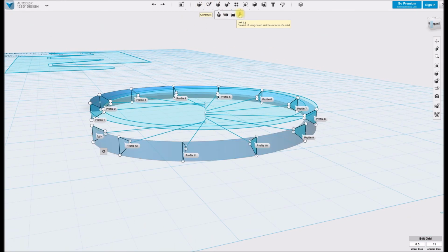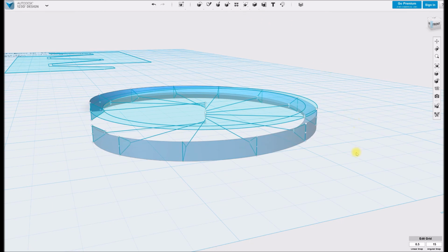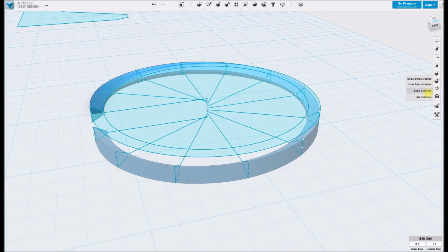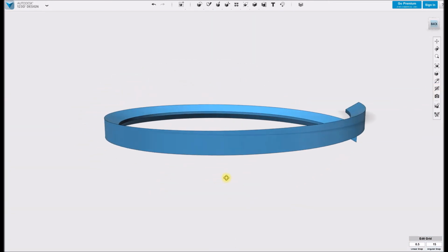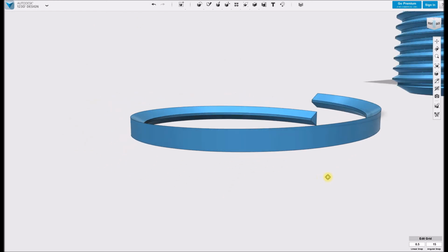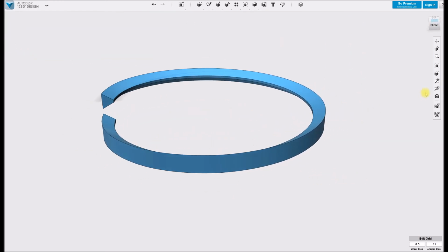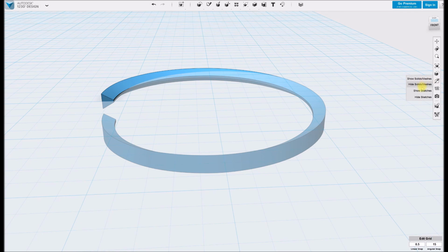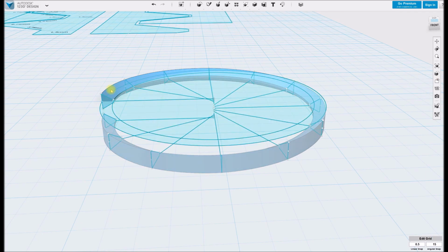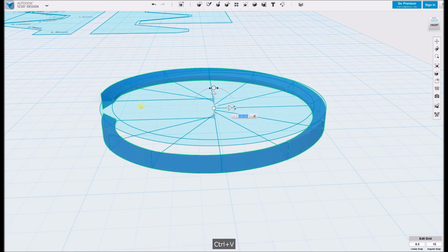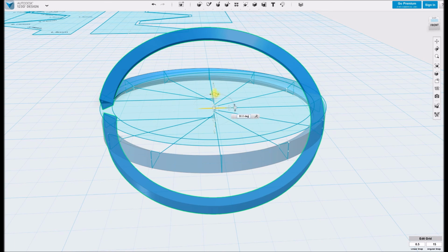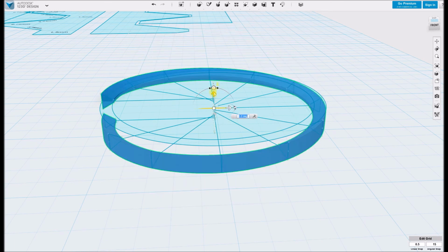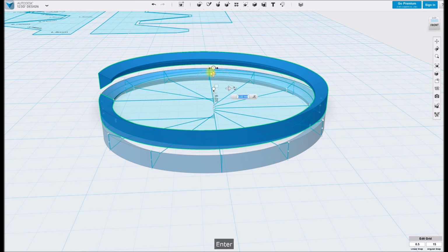Now click on the Loft tool. So now you can see you've got your internal thread there. Kind of looks like a helicoil. Show solids, show sketches. So same thing. Just copy and paste a bunch. You're going to want this to be a little on the tall side, just to make it easier for when you actually make the hex.